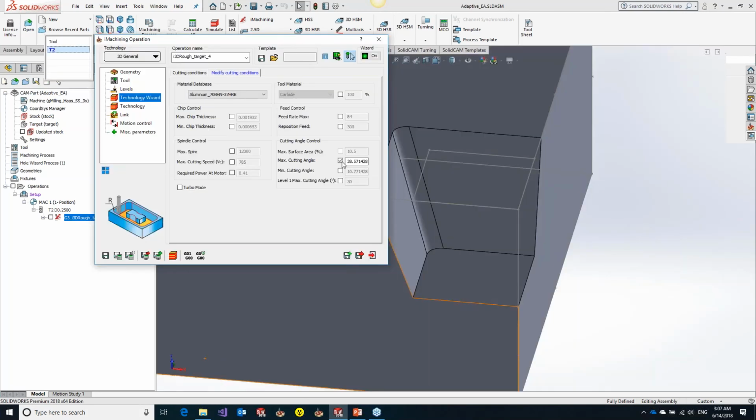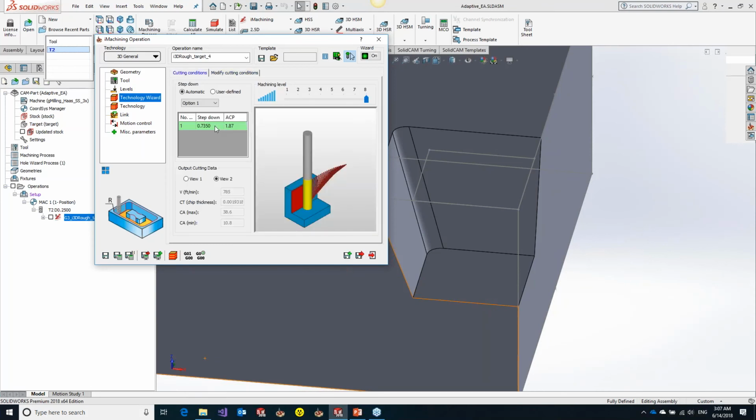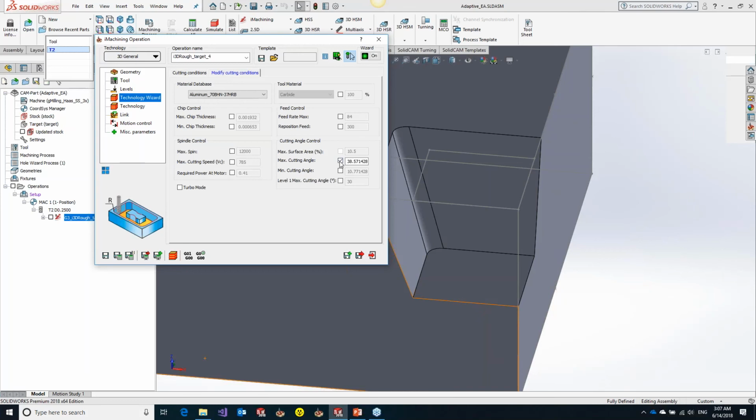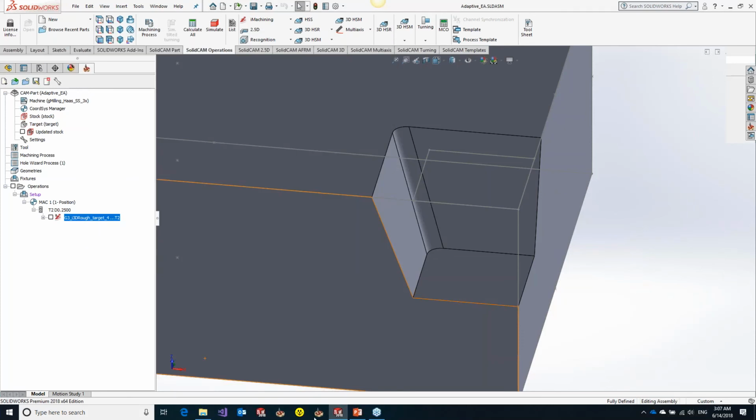So we think this makes sense. By default, use the wizard. We are going to adjust the engagement angle for each depth of cut. If the customer or the user or the technician knows, hey, I specifically want to run this engagement angle, if you say that, we do not do the adaptive engagement angle. Small feature, but very nice.